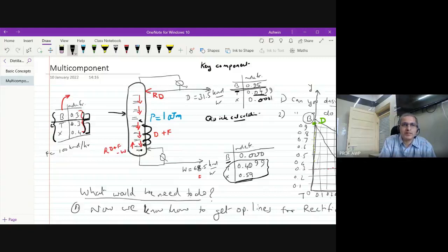I will say benzene is 0.3, and I will put some third component or a pseudo component which is 0.7, and let this pseudo component have properties of toluene, as if the xylene is not interfering at all in the benzene versus toluene separation. Do you agree with that?